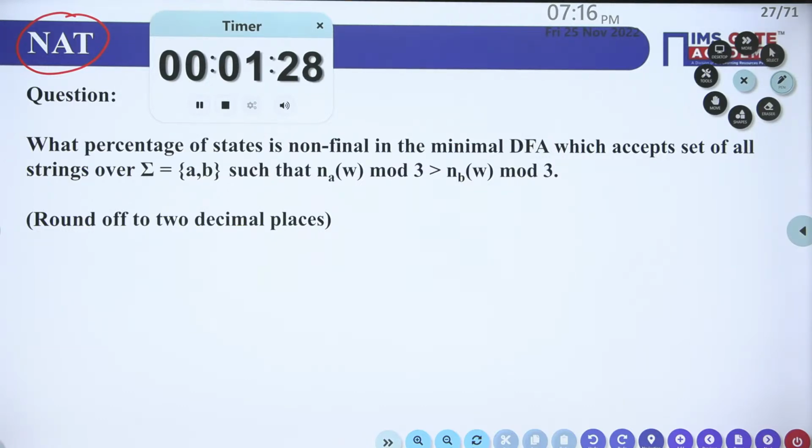Now, if it is equal to the depth of the flange, the neutral axis will lie at the edge of the flange, and then also it behaves as a rectangular beam. Whether it lies on the interface or inside, both will act as what, my dear students? In both cases, it acts as a rectangular beam. That is a good question, Ramakrishna. So no need to worry: when XU is less than or equal to DF, you should understand that the beam behaves as a rectangular beam.